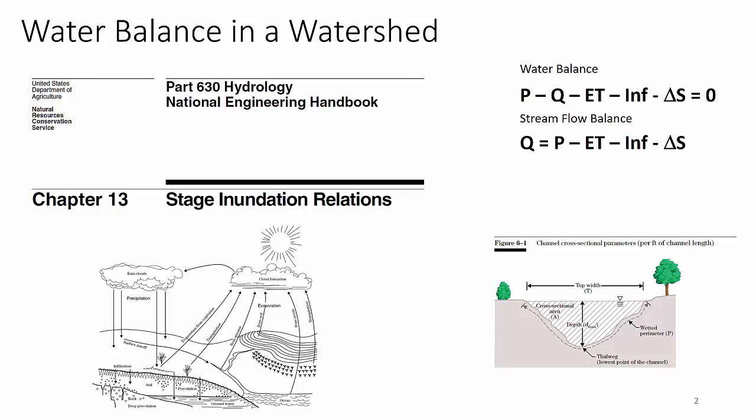We spent some time in earlier chapters talking about water storage on the land, in the soil and through infiltration, and also through small soil indentions. Here we're talking about channel storage, the storage of water in these flow conveyances. Flow conveyances are geometric shapes, and they have width and depth, and they have a wetted perimeter and a cross-sectional area. They have a deepest point. These channels can be 6 centimeters deep, or 6 meters deep, or 60 meters deep. But they all have similar characteristics.